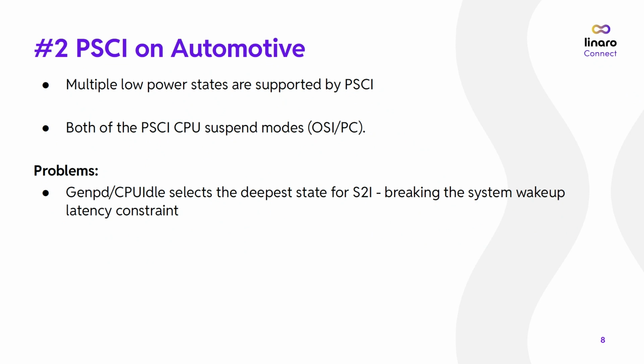I don't know if you're familiar with PSCI in those low-level details, but there's something called CPU suspend mode. There are two different ways of doing CPU power management: OS-initiated mode and platform-coordinated mode. In this use case, both of those modes seem to be used. You only use one at a time, but there seem to be reasons to support both scenarios.